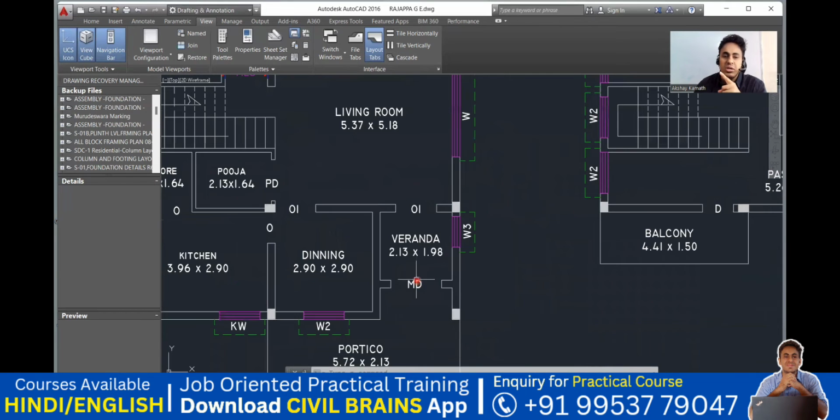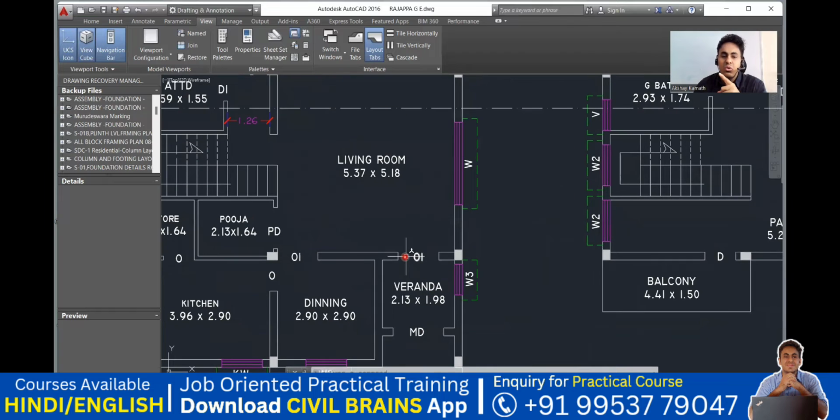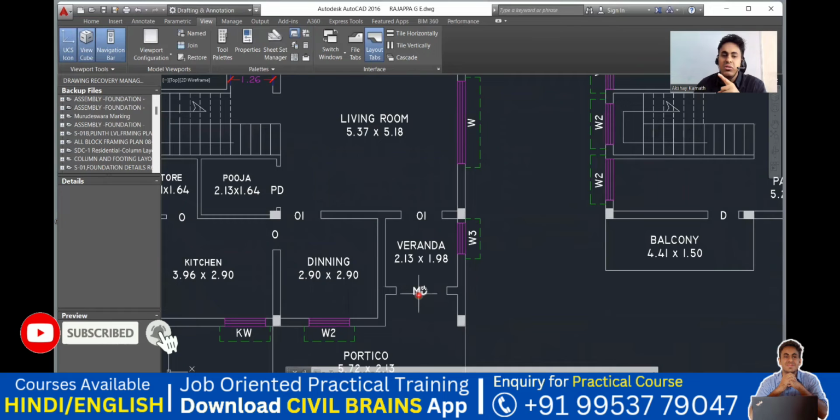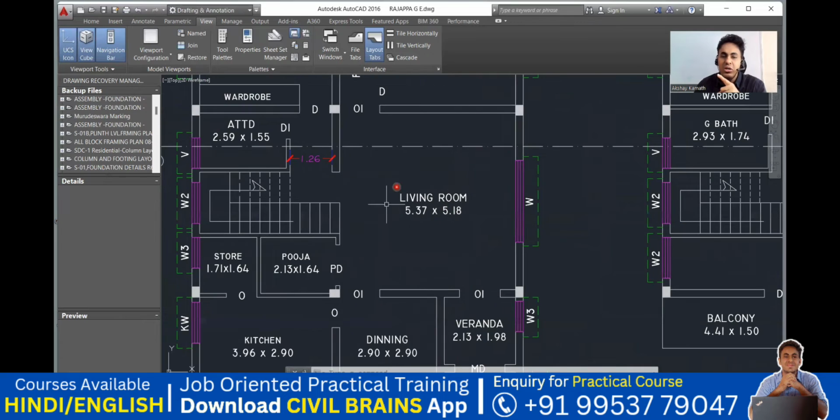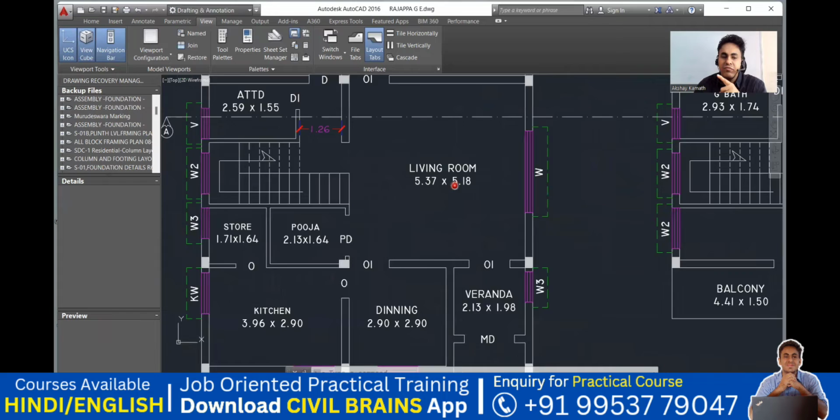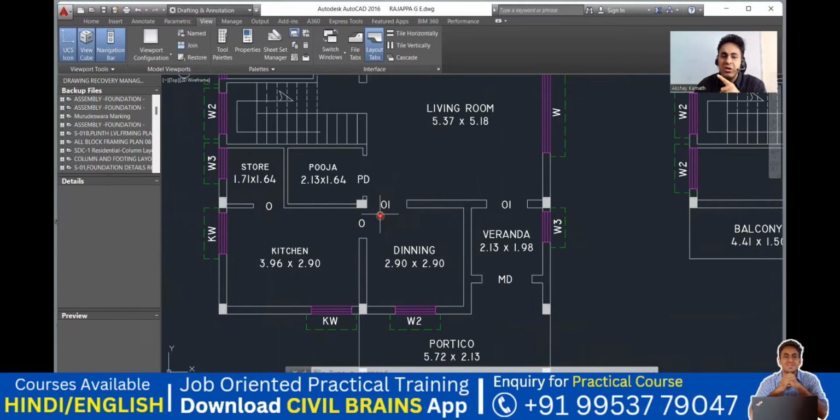It's a main door. You have a veranda here. So O1 stands for the opening. Again, you don't have a door here. You have a main door, right? Soon after that, you don't have a door here. They have given O1. And then you have a very big living hall, which is almost 5.37 by 5.18 meters. And from there again you come to this portion, you have an opening here.